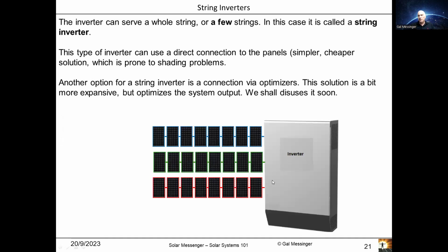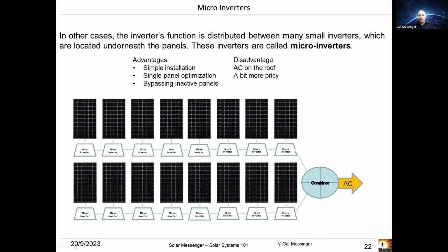It's very rare to see this anymore because any issue with one solar panel is going to really cause problems in the system. It's very good for small systems that you can actually touch the solar panels. Let's say if it's a ground array facing south on a clear field, maybe this is a good solution. Because you can shovel the snow down with like 10 minutes of work, and the solar panels are usually in the same illumination. Another way, as I mentioned, is to put microinverters.